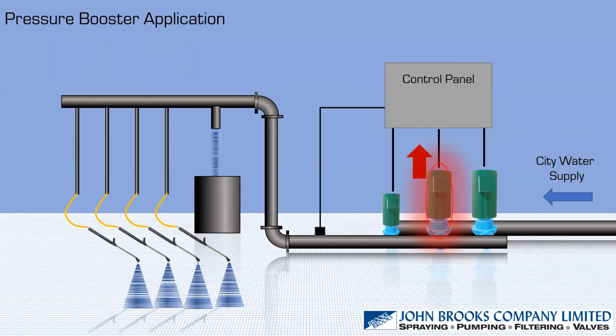Would that be a concern? I probably would. Adrian, have you seen that? I probably would want a bypass system that would go from the city water supply when we're in a very low flow situation. That bypasses the pumps completely, so we're not pumping through them. Yeah, I completely agree with that.